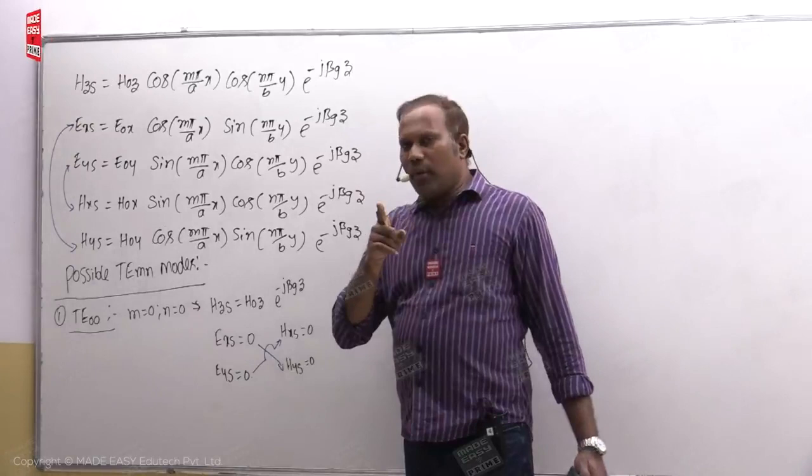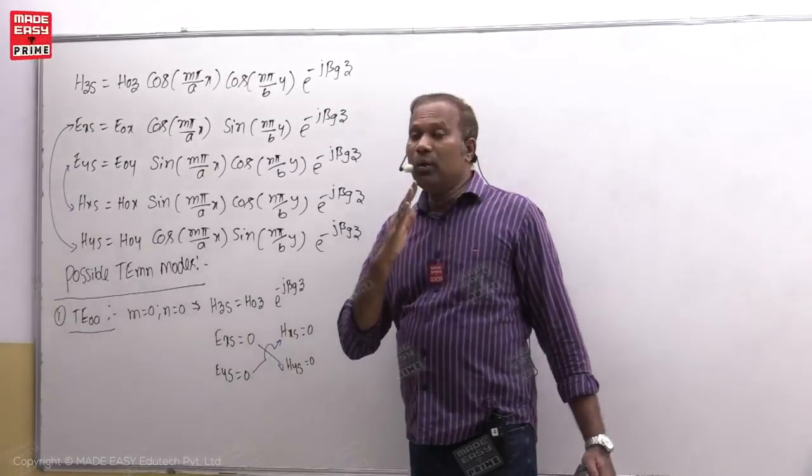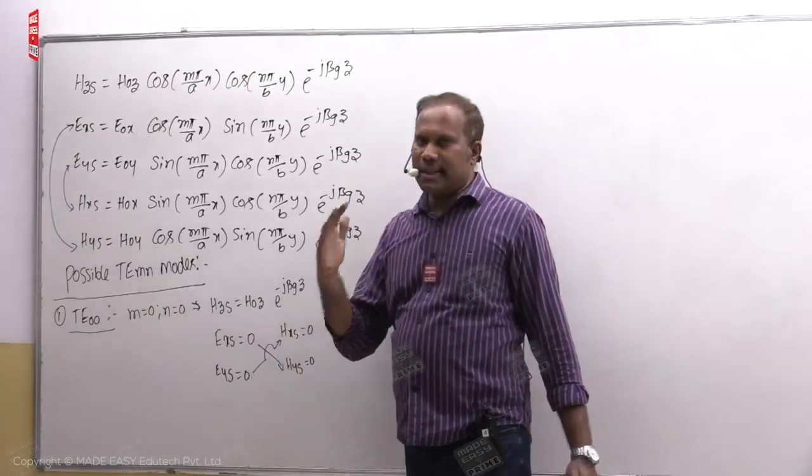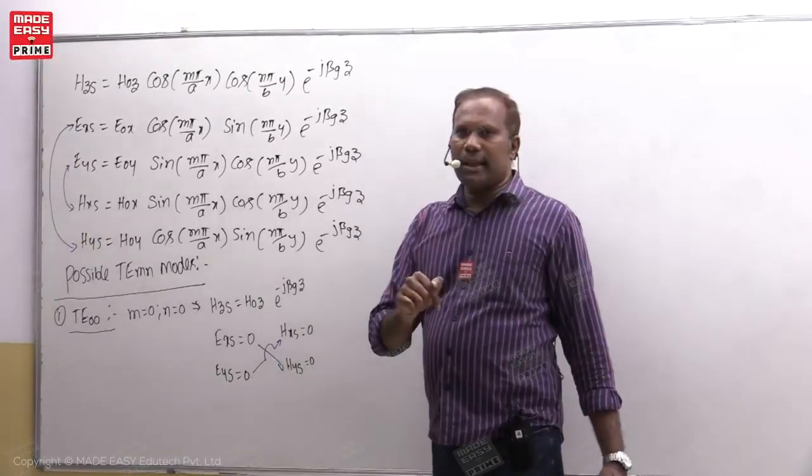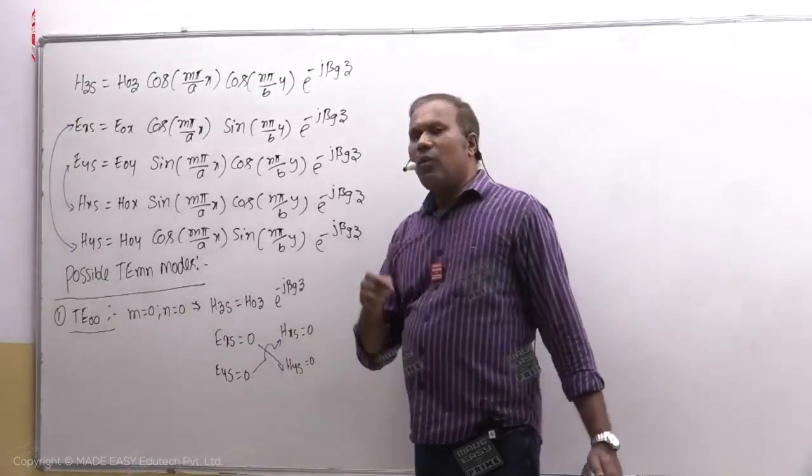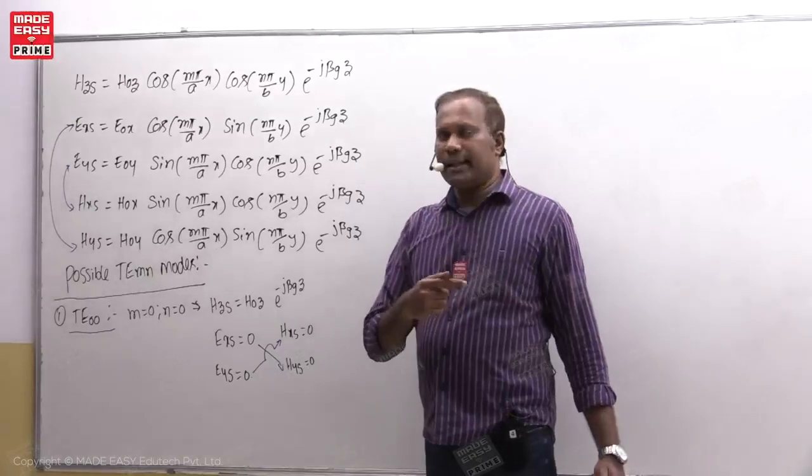Power cannot be carried in TE00 mode. No power flow is there because field equations are 0. If there is no power flow, then you say the mode does not exist. Mode exists means there are field equations which carry the power in z direction.